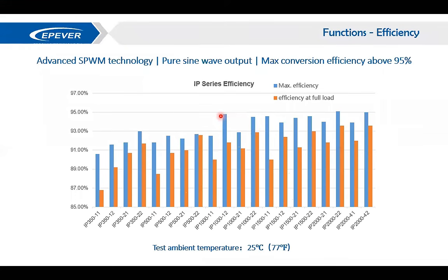Okay, now the efficiency of the iPower series. As discussed in the previous slides, by efficiency, we mean what percentage of the power that goes into the inverter comes out as usable AC output. And we all know that nothing is 100% efficient. And as you saw, there are multiple conversions. First it's converted to AC, then DC, then rectified. Then with this PWM it goes into AC again. So naturally you will have some losses in your system because you are doing some conversion.